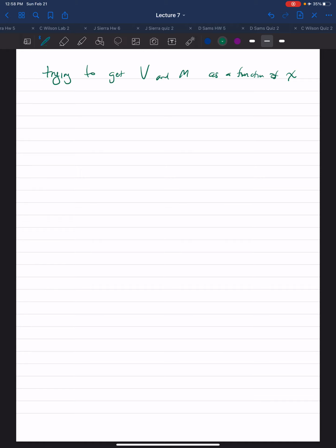So similarly to the previous example problem, for rectangular loadings, which are represented by base times height, as a function of x, there's simply your intensity, which would be 2 kip per foot times whatever distance x you're working on. So this would be represented in this problem as 2x.